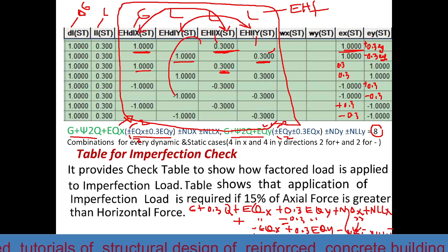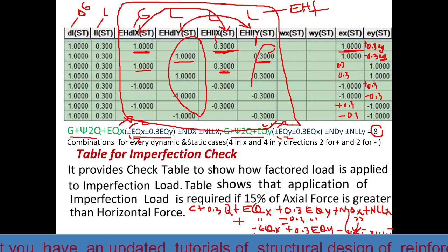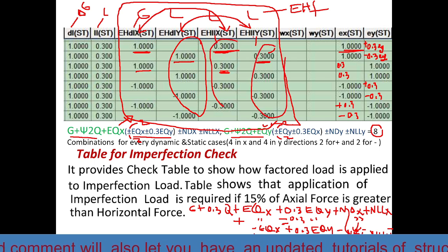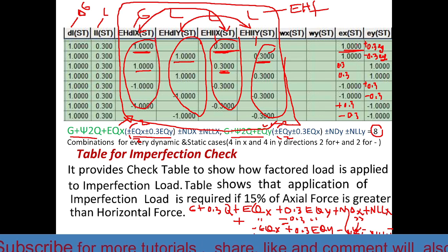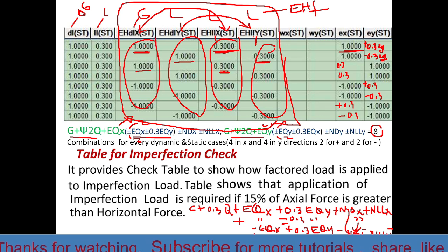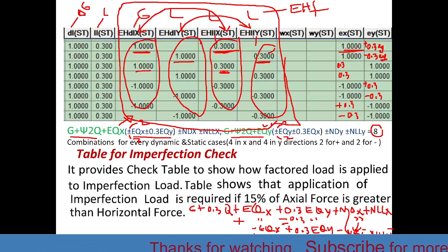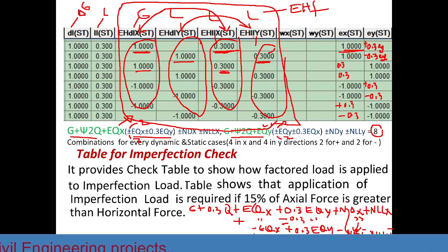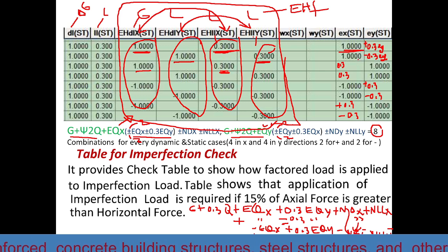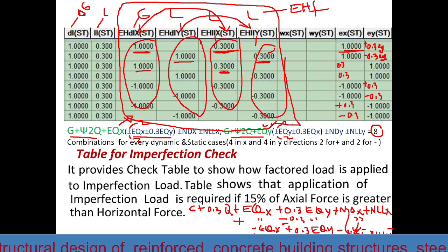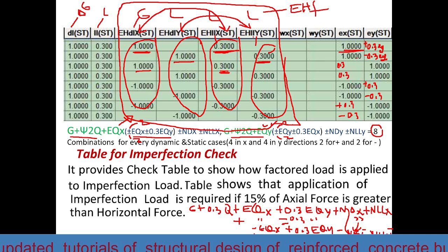Here, this one with this one, and this one with this one. And also similarly, if this is in x direction, we need to combine it with seismic load in x direction. And if this is in y direction, it will be combined with the seismic load in y direction.